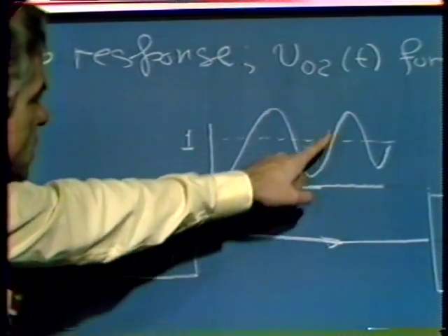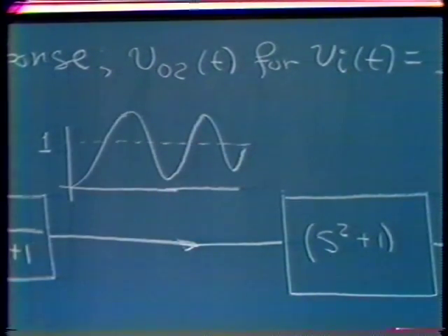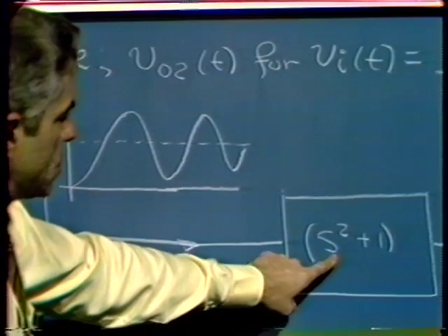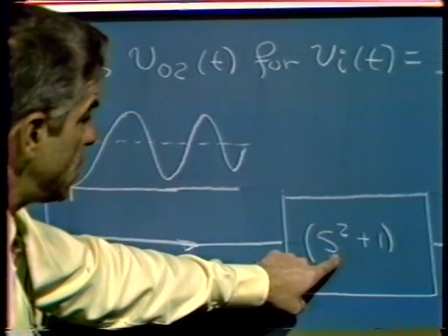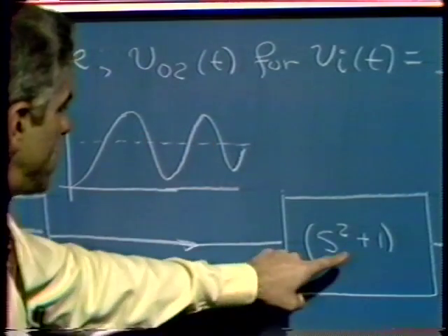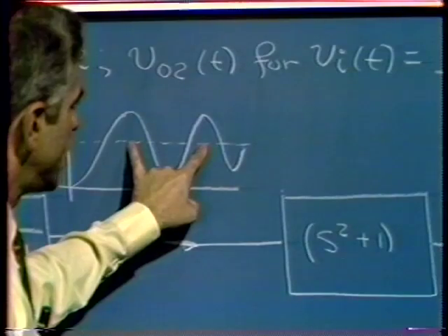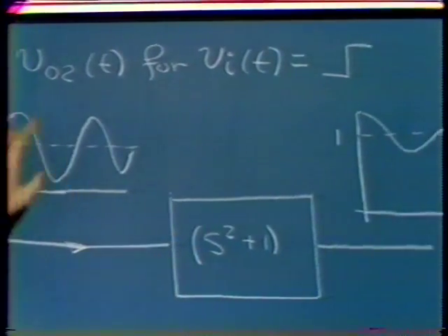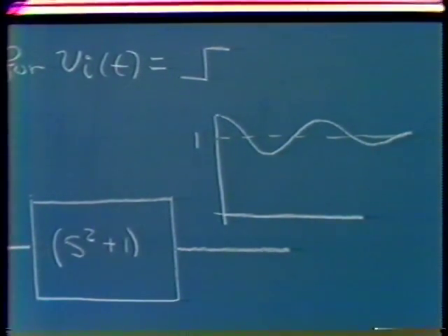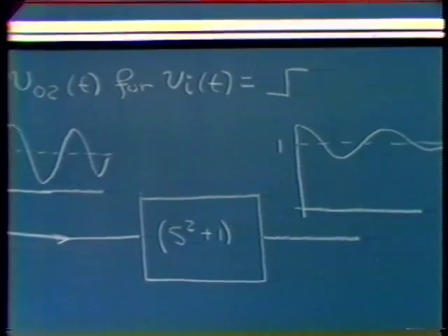We apply that signal, which is very nearly a sinusoid with just a small amount of damping, to a pair of zeros which are located at very nearly the frequency of this natural response. We have a pair of zeros located at a frequency that's very, very close to this frequency of oscillation. The net result is they very nearly cancel out the amplitude, or attenuate almost perfectly the amplitude, of this oscillation.